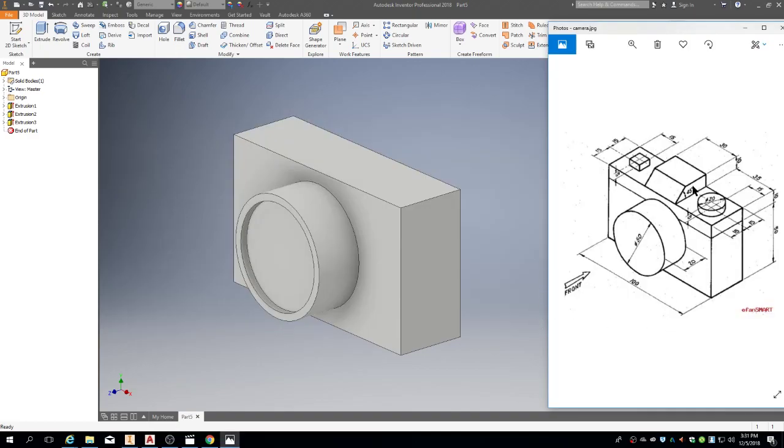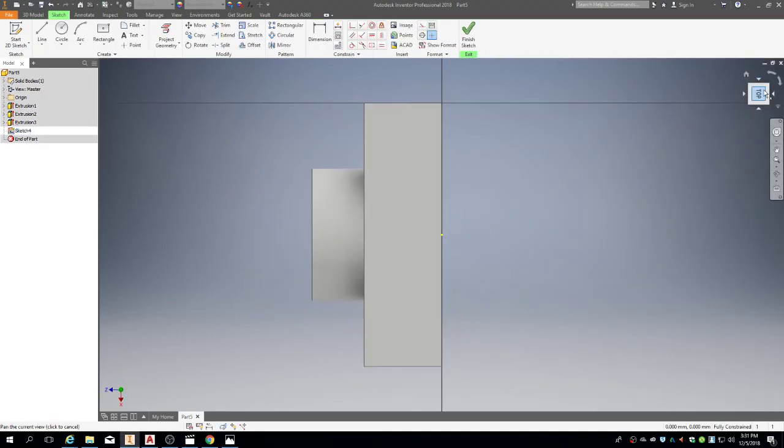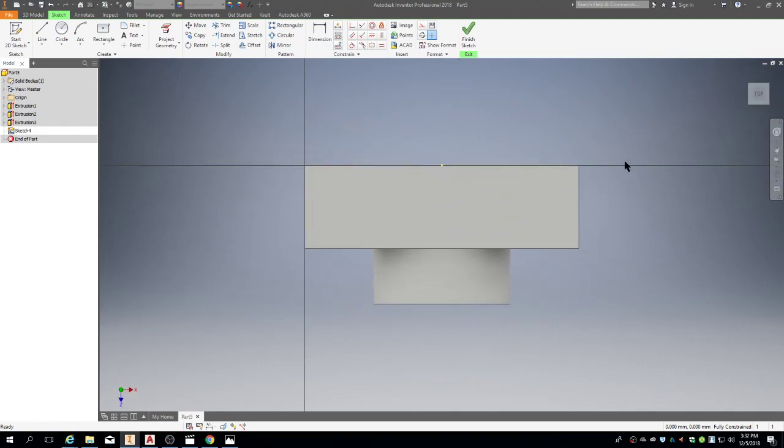Away we go. We want to create some surface up here with a twisting dial and a shutter button that you're going to press, and perhaps a light or viewfinder up on top. Your choice, your style. My suggestion is stick as close as possible to the way they do it here. And we're going to create on this surface a new sketch. Rotating it using your orbiter, hit the arrow up at the top so it orients the way that looks useful to you.